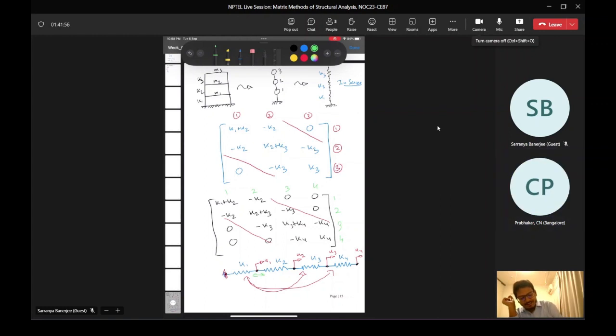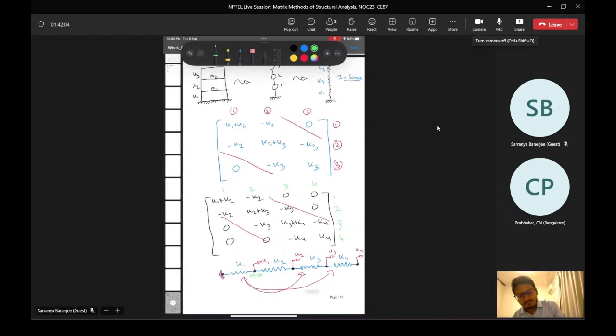So now again, from a basic truss problem to a beam problem to every problem, what we are discussing is that the column represents the displacement and the row represents the resistance. The resistance means the stiffness multiplied by the displacement means the force. By resistance I mean the participation of the stiffness. So we were moving the one element U1, right?